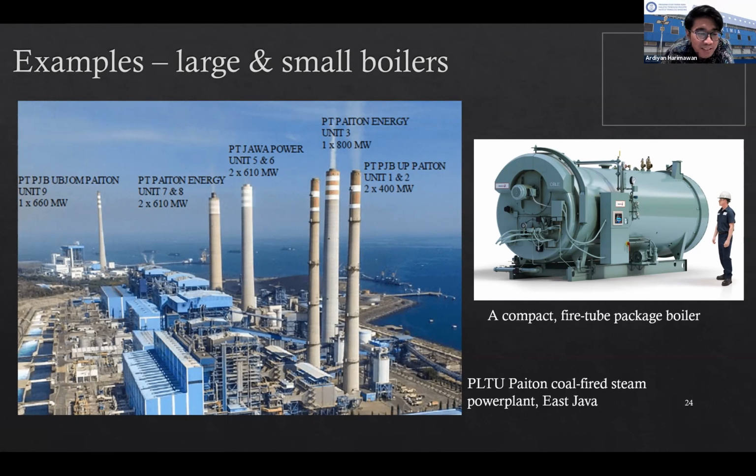Actually, while Pak Hendra was explaining, I was WhatsApping with Pak Miki asking about ash fusion because I'm curious. Basically, ash fusion is the phenomenon when we have very high temperature, the ash will be converted into very small particles. It's basically like the melting down of the ash. If the ash melts down, it goes up with the flow of the gas.